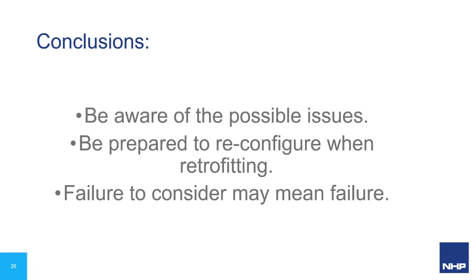You need to be aware of reduced torque capabilities of high efficiency motors, especially for fan applications and heavy duty starts. When replacing an older motor, either consider rewinding or be aware that the existing switchgear may not be appropriate for the new motor. Always consult the technical information and manufacturer's recommendations. Failure to consider all of the factors may lead to a catastrophic switchgear failure, and this may have serious safety and financial ramifications.